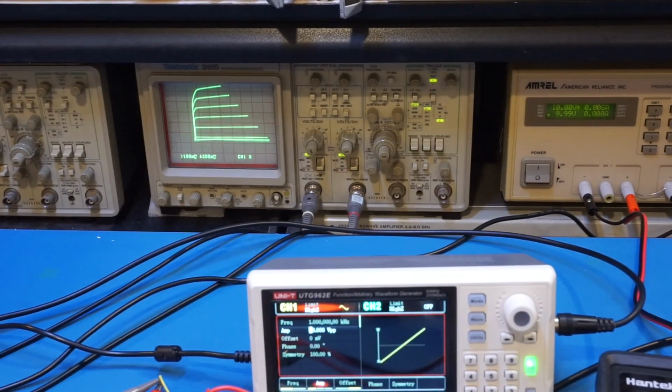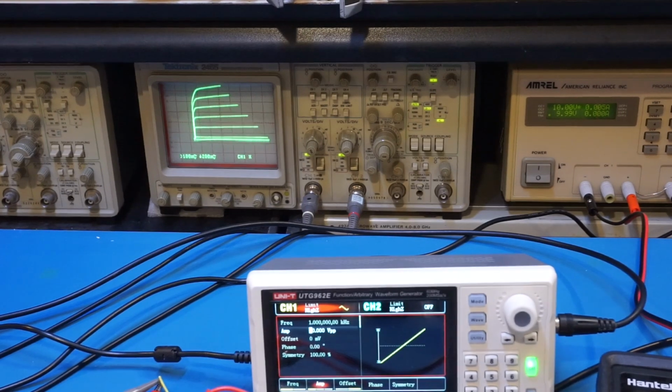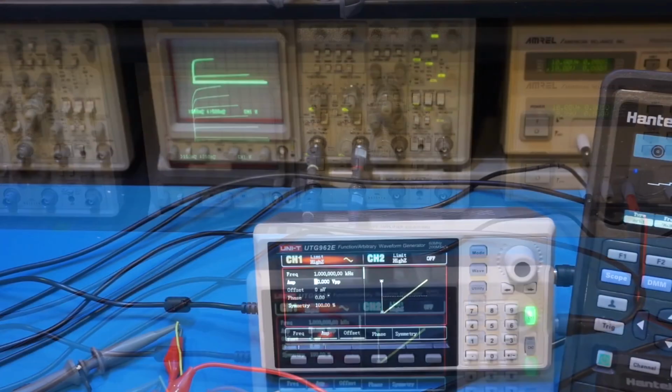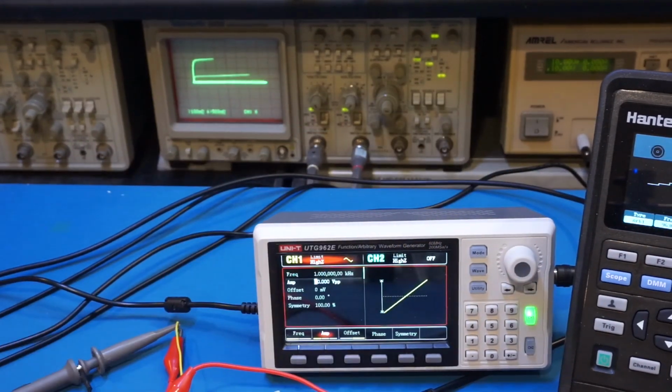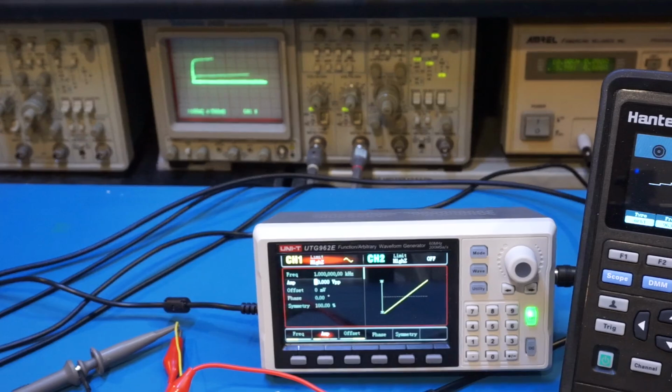Of course, to do some quantitative analysis, you can turn on the cursors on the scope and do some measurements there. And of course, we can use the same setup to measure the characteristic curves of a MOSFET. And now on that breadboard, I swapped out our 2N3904 with a 2N7000 MOSFET. And you can see that we have a different set of curves being shown here.